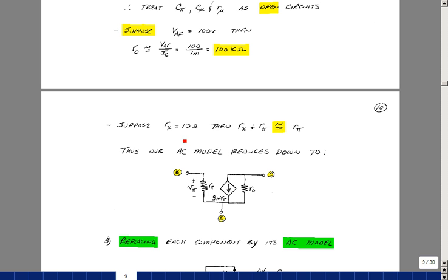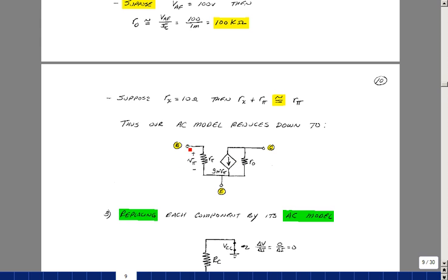Suppose that r_x is around 10 ohms, then that's in series with about 4K, so basically it's about rπ. So we're pretty much back to the model we had used in 302 with an rπ, a gm vπ. You could also use beta naught I_B, the AC beta times I_B, and then now a parallel resistance with our current source to take into account the slope of the VI characteristics.